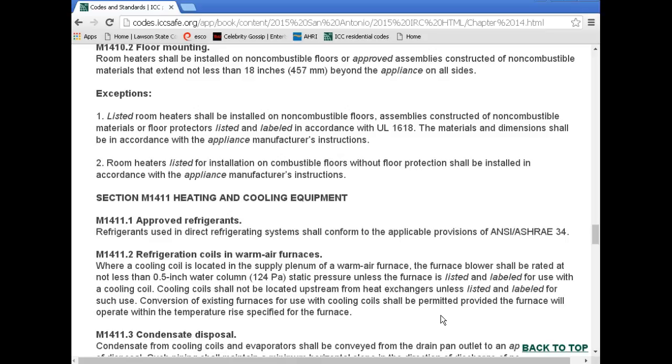The problem with this is in the summer, cold, humid air loaded with moisture is going to hit that big steel heat exchanger and rust it out. Has to be downstream. Does that make sense?